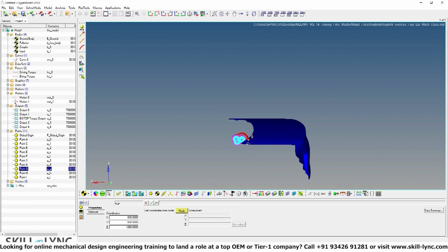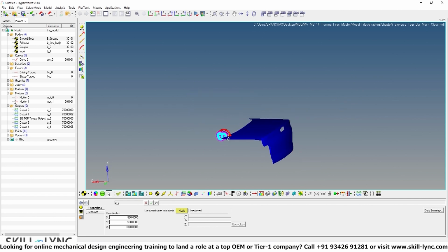Instead, I wanted to create it at the right location, which is why I input these numbers. When you're building a model from scratch, you have to experiment and get the right location of this CAD based on where your input model is. Once you've got your trunk lid here and there were no importing errors,